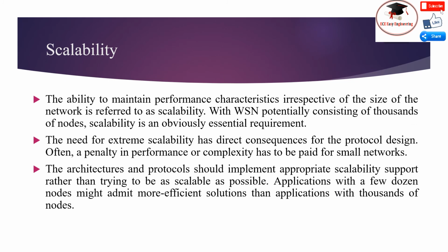Scalability. The ability to maintain performance characteristics irrespective of the size of the network is referred to as scalability. When a wireless sensor network potentially consists of thousands of nodes, scalability is an obviously essential requirement. The need for extreme scalability has direct consequences for the protocol design.